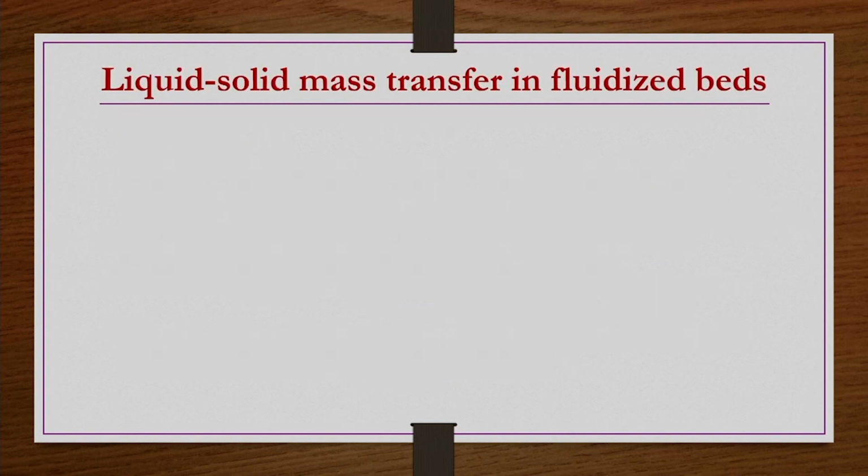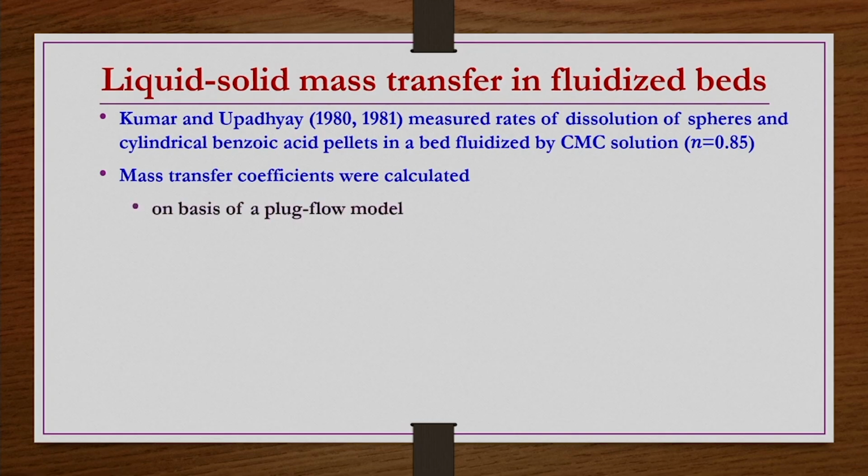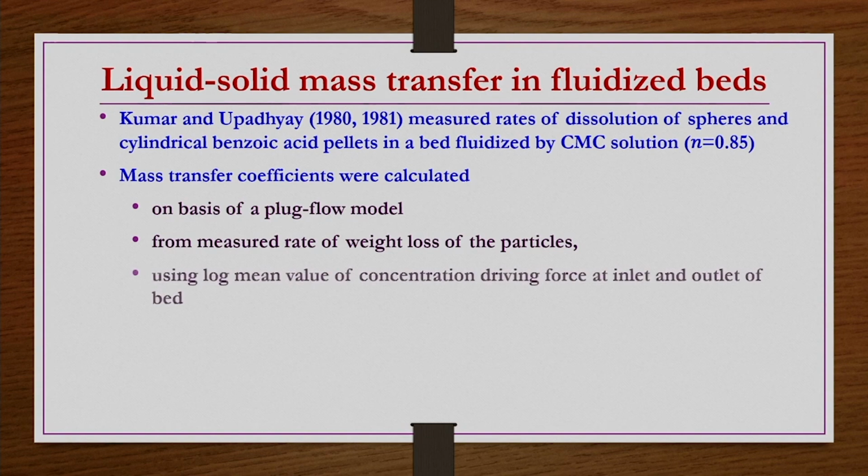So, liquid-solid mass transfer in fluidized beds, here also very limited studies are available. Kumar and Upadhyay measured rates of dissolution of spheres and cylindrical benzoic acid pellets in a fluidized bed by CMC solution of only n value 0.85. Then they measured the mass transfer coefficients on the basis of a plug flow model from the measured rate of weight loss of the particles, using the log mean value of concentration driving force at inlet and outlet of the bed.